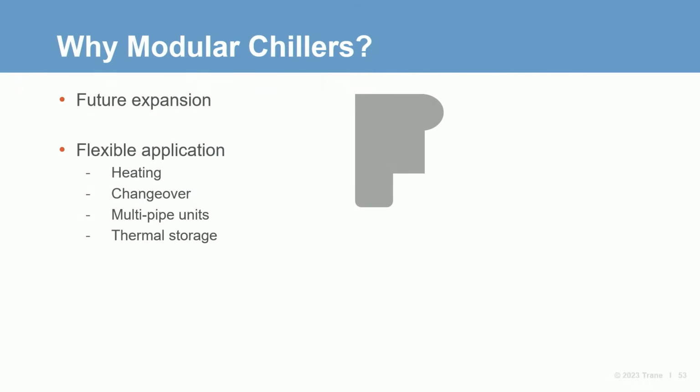Let's assume this represents the building footprint of an upstart brewery. When the facility expands, shown in yellow, a modular chiller lends itself to incremental capacity increases. Adding another module to the existing chiller, especially with forethought during plant design, can be simpler than adding a packaged chiller. The headers and plant piping should be sized for the maximum expected capacity up front. Structural supports and the base frame are installed early on as well, but the equipment costs can be delayed until the capacity becomes needed, especially if growth differs from forecast.